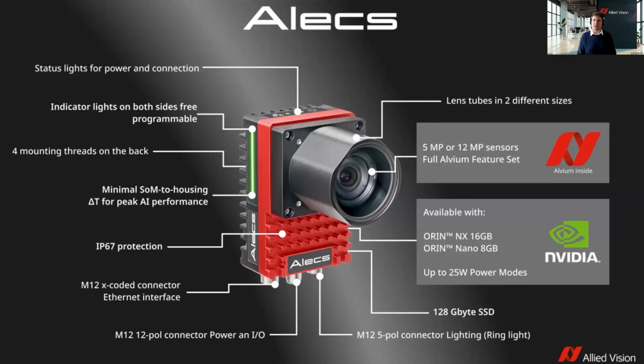We combine this with the NVIDIA SOMs, so system on modules from NVIDIA. And we decided to go with the NX Orin versions, for sure with the highest RAM possibilities, and also with the Nano version, also with the high RAM option here with 8 gigabytes. And each SOM, not only from NVIDIA, has dedicated chips which you can enable step by step. And for this, there are different power modes available.